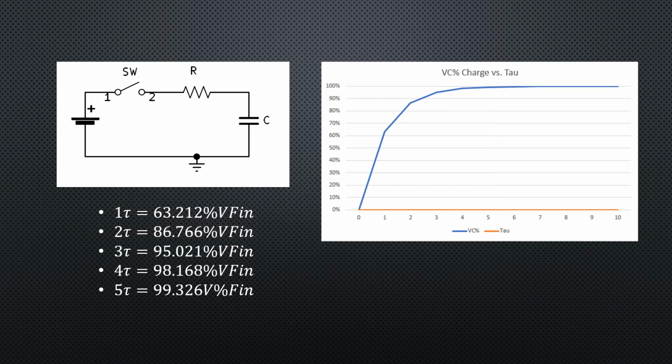Now, if you wanted to, you could go in there and graph the points in between 1 tau and 2 tau, or graph it all at like 0.25, 0.5, 0.75, and then 1, and then all the way through, and that'll get that curve a little bit smoothed out. You can see those points there. You could up that resolution by graphing more data points. But the intent of this is to show the relationship of tau and time, and that 5 tau gets us a fully charged capacitor.